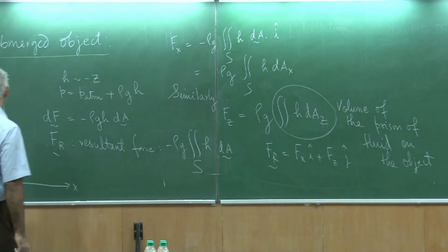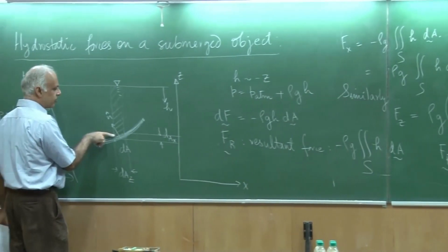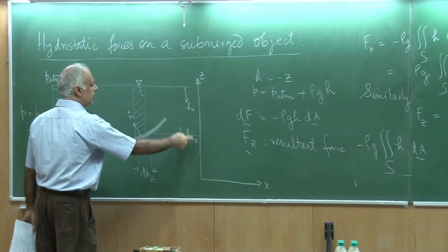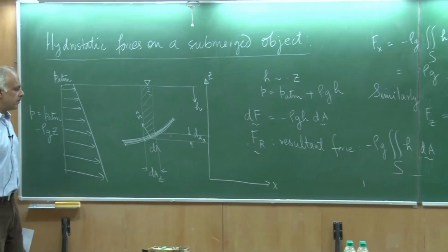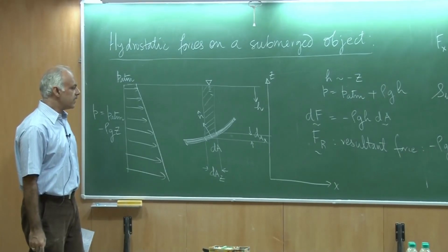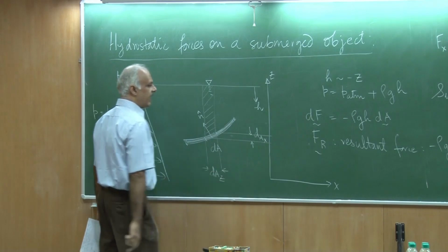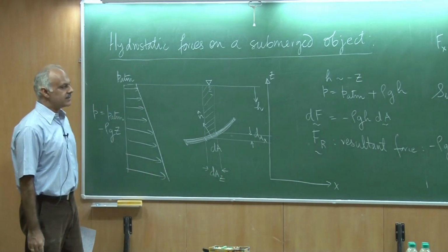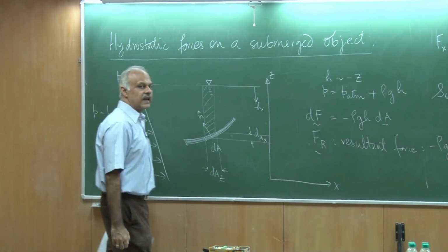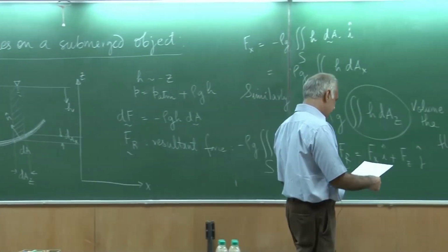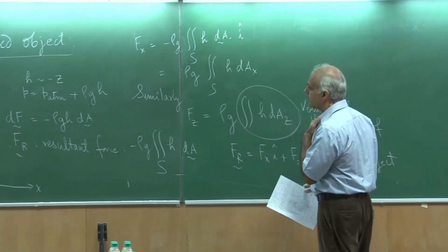And likewise, when I want to calculate the force in the x direction, then I am going to integrate the volume of the prism of this fluid, which I can see in this projection, and effectively the weight of that. Okay. So, that is how I would calculate the force on the submerged object.